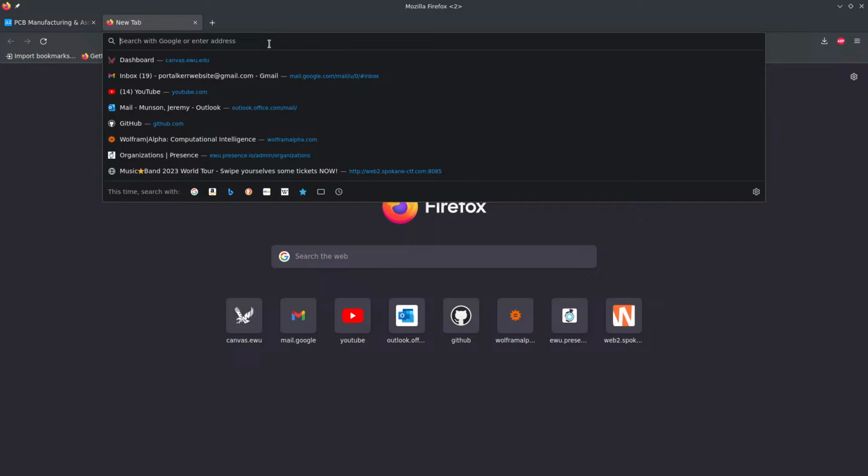Then how do you decide what chip you want to use? So that is an art in itself, and the only way to get good at that is literally to go and sit down and try to find a chip to use. If I already know a chip I want to use, that makes it easy, of course. But chances are I don't. What I do is go into Mouser or DigiKey, and I just start doing the parametric search and looking around and trying to see what's out there.